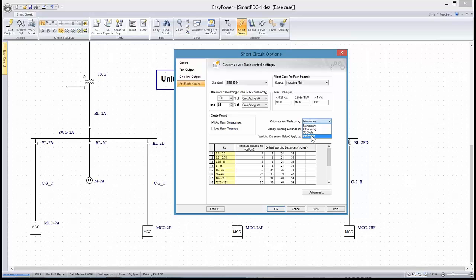What we recommend and suggest as a more accurate scheme is to use integrated for faults that have the potential to extend beyond half cycle, 5 cycle, or 30. This particular setting has the ability to incorporate the energy produced by each phase at each stage of current level at 5 cycles, 30 cycles, and half cycle.